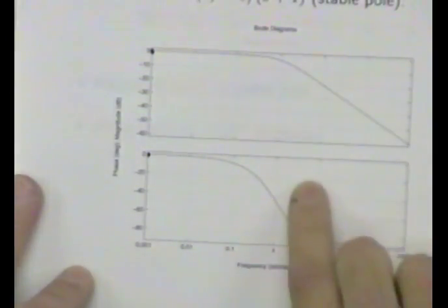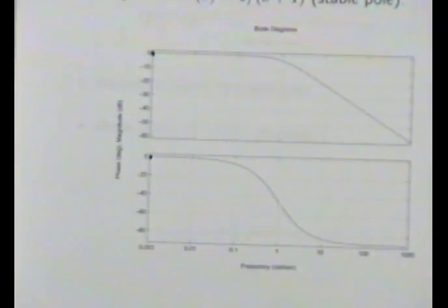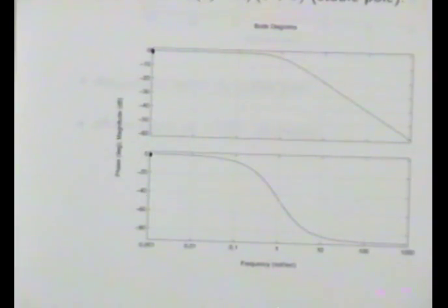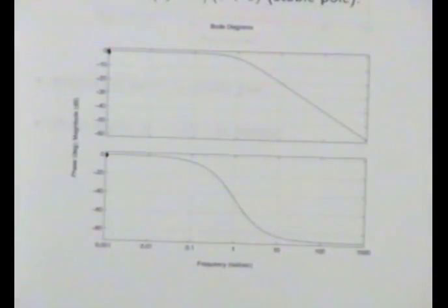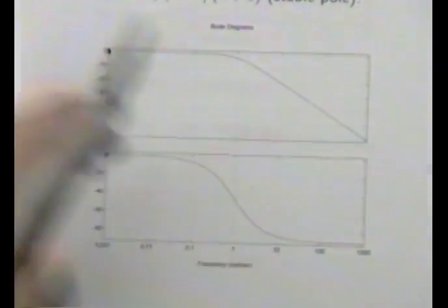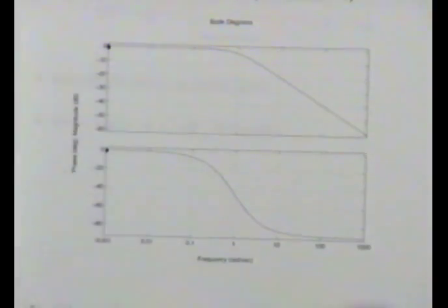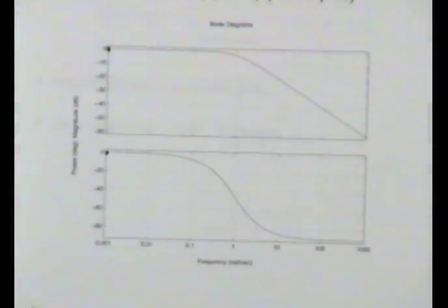Notice that for his choice, p is -1, so 1 over root absolute p squared, sorry, is 1. And so the magnitude at 0 frequency is simply 0 dB, right? 20 log base 10 of 1 is 0. So we found this data point at least.